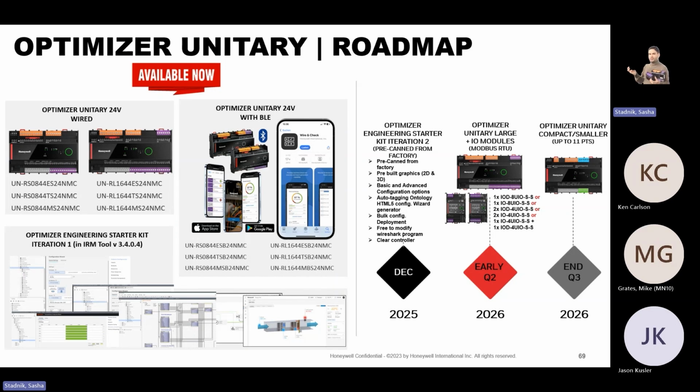Why do you need that separation? How many processors will this one have? Two cores. How many processors does this unitary board have? One. And it's limited. Do you really want to use more than 32 points on the control system without that much power? You don't want that because it's going to become slow. It's like your mobile phone or your laptop. You start to limit the RAM. If you have a limitation of memory, what happens? You cannot run anything, right?